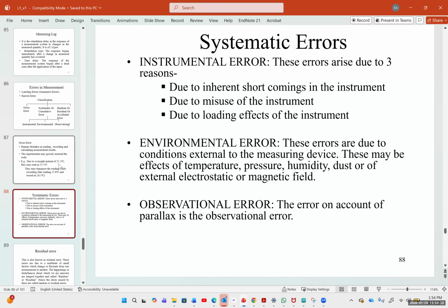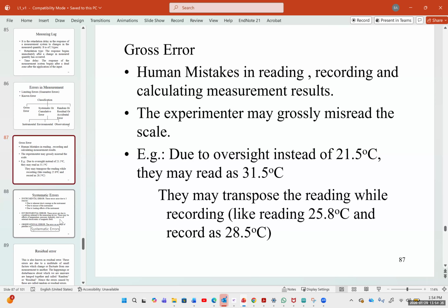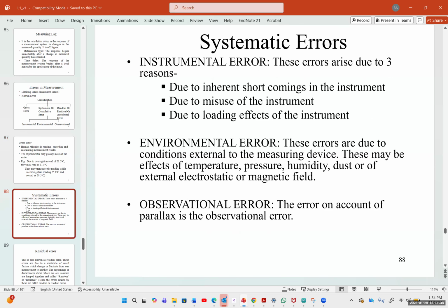Now, the way to counter this error is to do multiple readings. So we would ask the person to read the value every 5 minutes or every 2 minutes, or read it 3 or 4 times. Okay, that's one way to get rid of it. Or have 2 persons read, so someone to check and double check. Same thing that someone does when they do a blood test.